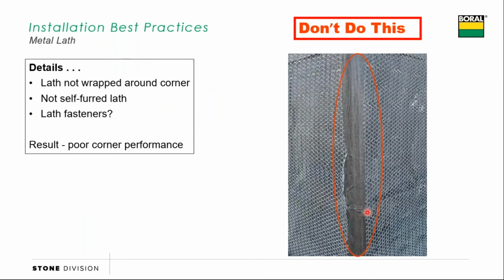We do not want to start and stop at a corner. In doing so, there's great potential for cracking in our corners. Two things. New buildings, as they settle, do not settle evenly, and that uneven movement usually shows up in the corners and can crack the cornerstones. The other problem is when the sun hits one side of the building, this wall begins to warm up and expand. And as the sun moves in the afternoon to the opposite side of the building, now this wall is warming and this wall is cooling. And that differential movement can cause cracking in the corners.